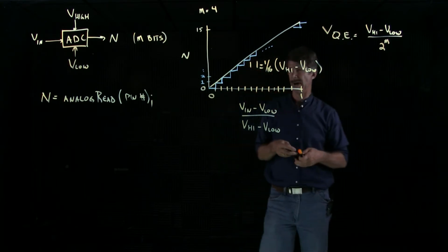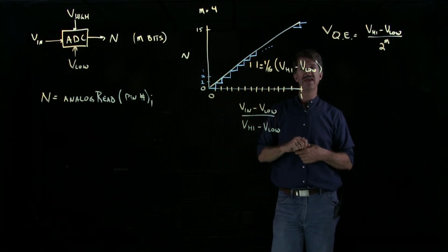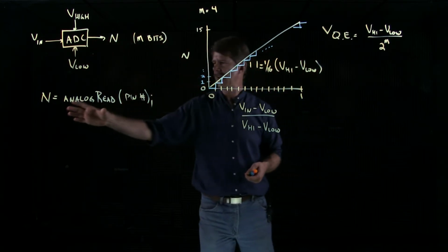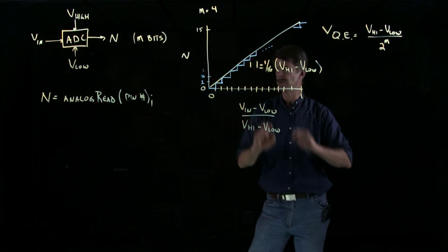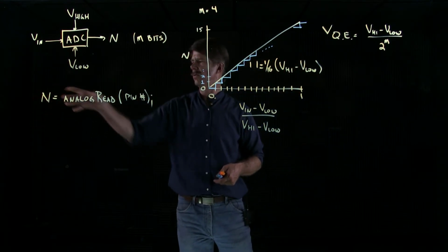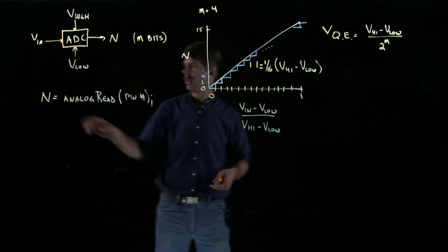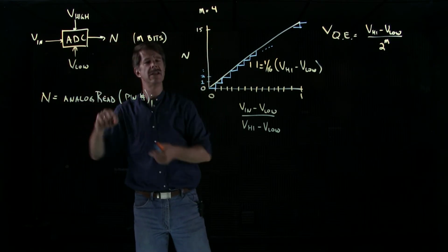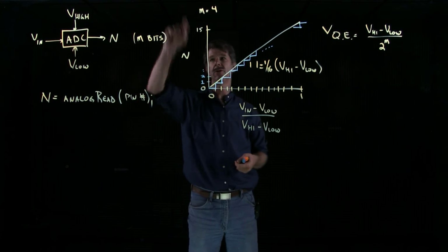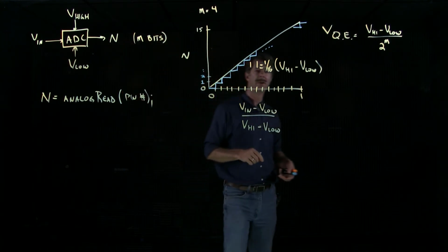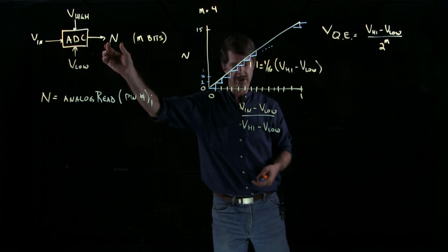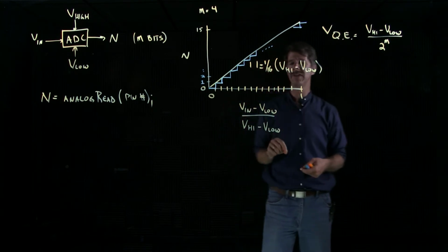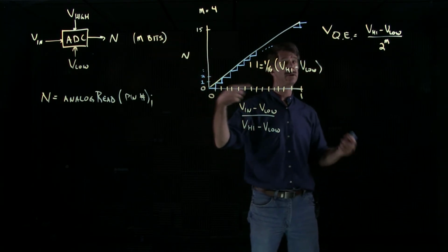And then the last thing to think about, which is now completely on the board, is if you use a certain pin on your Arduino and you attach to it a sensor that is going to provide a voltage, you read in your Arduino with this analogRead command in your sketch, and you get a number. You can go look up what integer range you can get in your Arduino so you know this scale. You know how many bits are in this number. You want to take this integer and turn it back into the best approximation you can, given this quantization, of Vin. You have to run this process backwards.